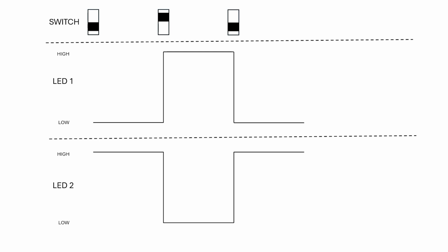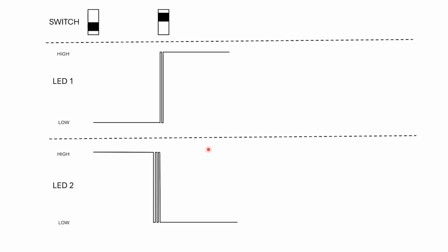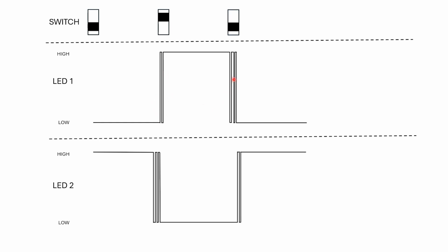But appearances can be deceptive. No switch is a perfect device, which means that a combination of vibration and imperfections in the switch will mean as you slide the switch, the connection between the slider contact and the terminals could be momentarily broken and remade several times over a short period of time. The same thing will happen when we slide the switch back. This behaviour is known as bouncing because of the way the signal bounces back and forth.